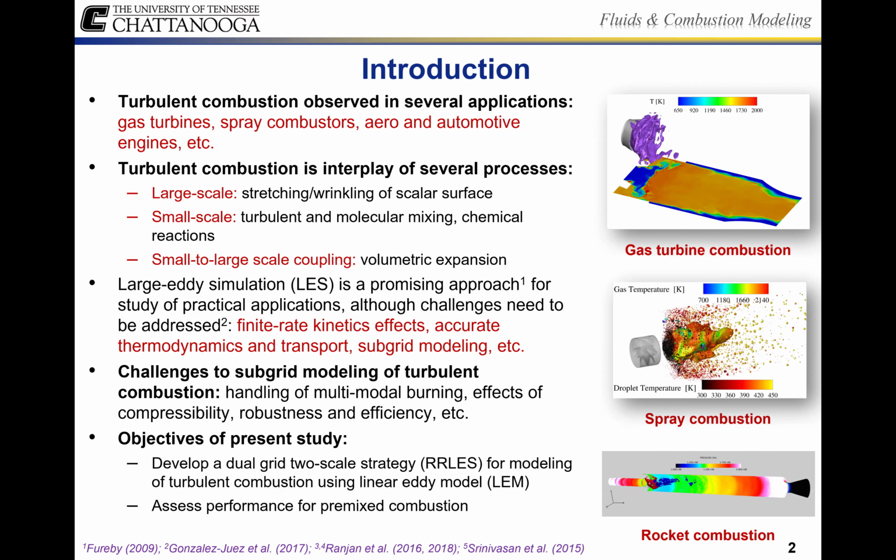All right, so the objectives of this study were to develop a dual grid two-scale strategy for modeling of turbulent combustion using the linear eddy model as a base, and then we're also going to assess its performance for premixed combustion.